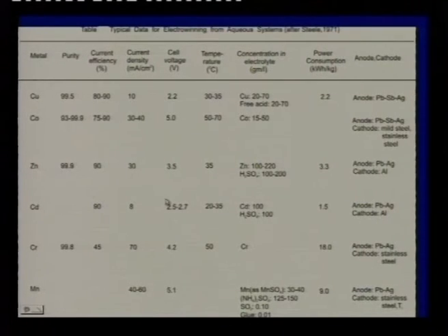Yet, the metal you produce really is not required at that purity for most applications. The most important application is galvanizing, which would do with a lower purity, but we can't help it. We have to put pure zinc. In some cases like copper, we settle for a slightly lower purity, but it has to go for electrorefining later on, because you want to recover the precious metals from it.